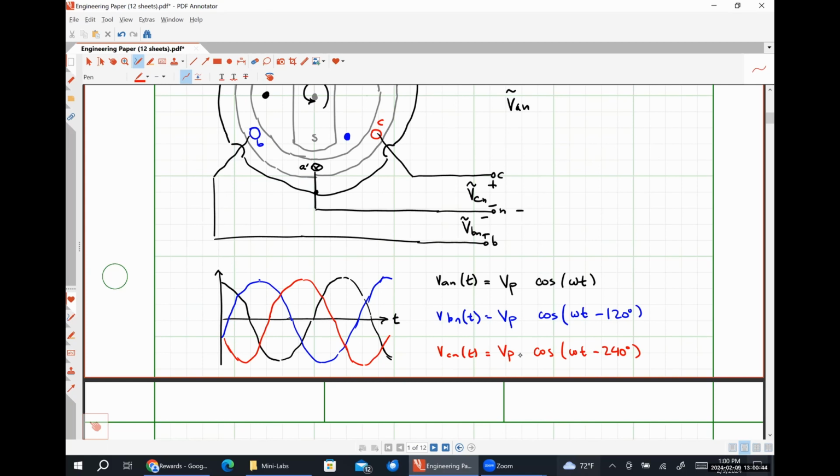So an unbalanced voltage source doesn't really exist. And I say that because it literally requires errors in the manufacturing to generate. As long as the system is built consistently, you're going to have a balanced three-phase generator. So the voltage that you're being provided will be balanced. The unbalance is then going to come from any change in impedances that are connected.